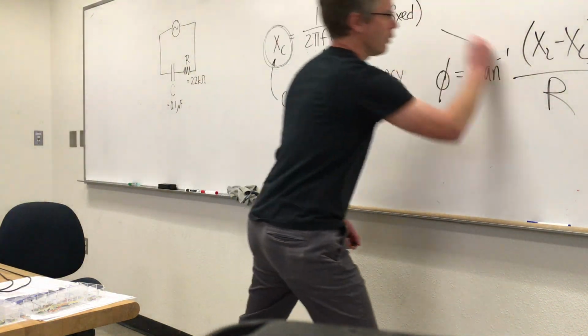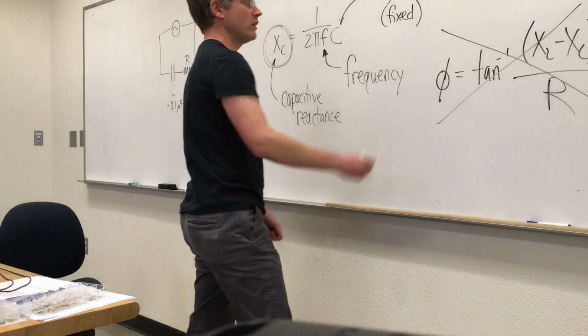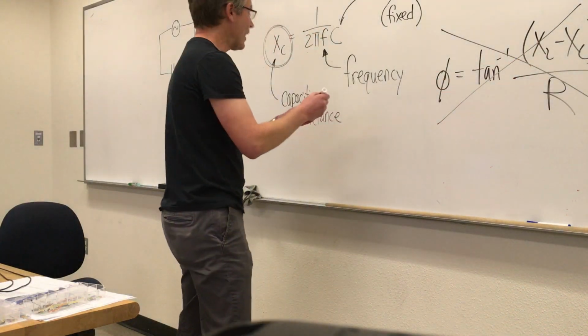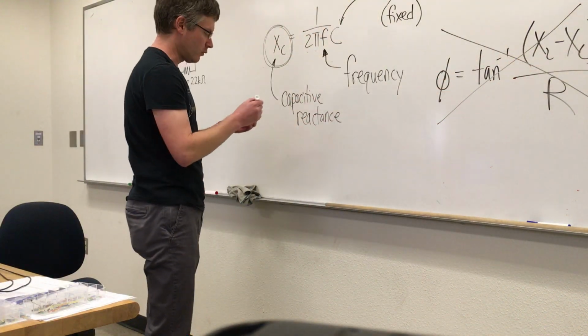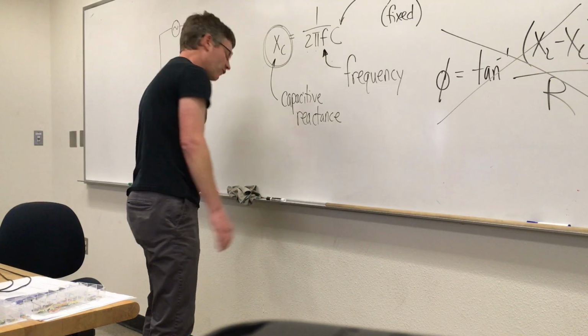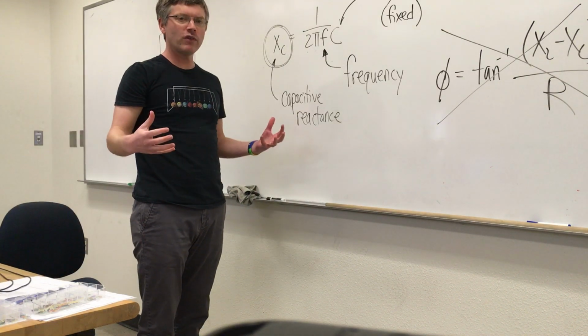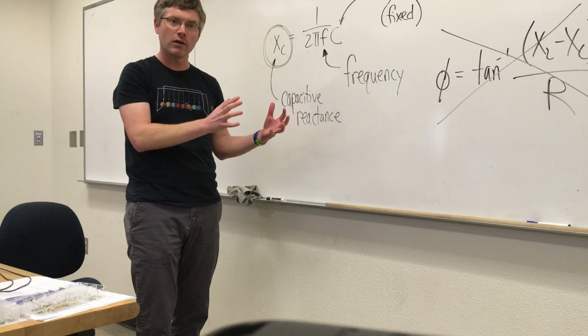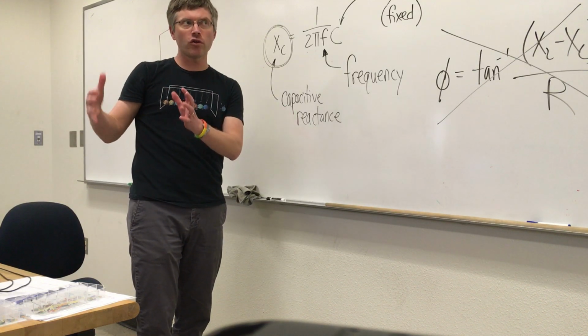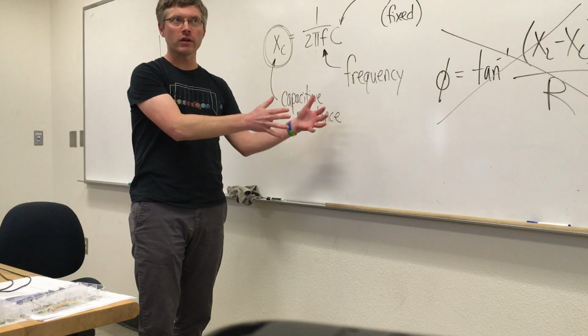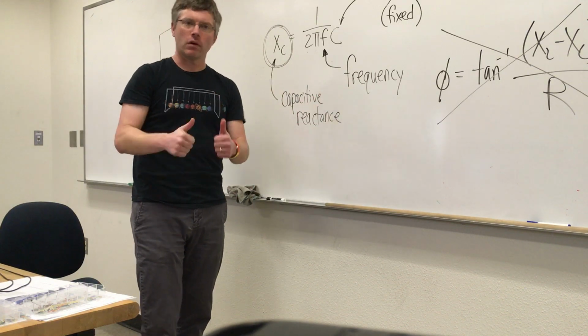But it's not important. All we need to know is that it's directly proportional to how big that capacitive reactance is. And so the idea that lower frequency gives us a larger phase angle, a larger time shift of voltage applied to the circuit versus current through the circuit, checks out.